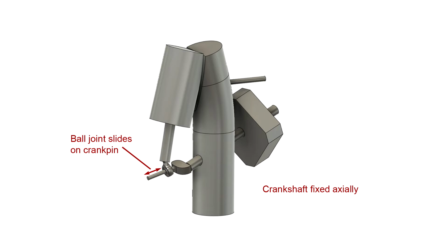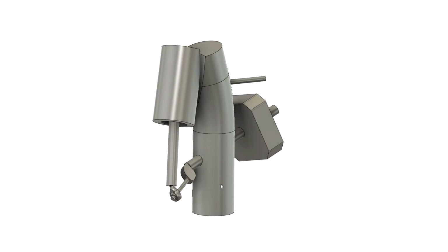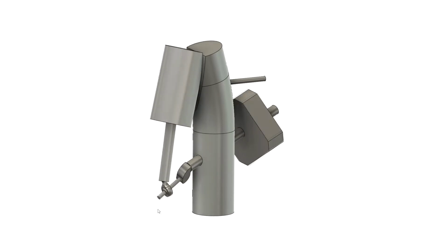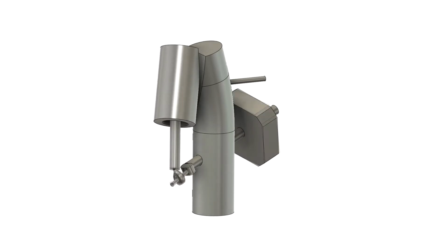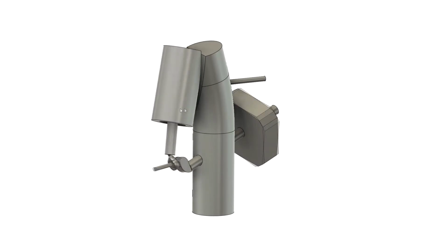Okay, let's try the obvious and let the ball joint slide on the crank pin. It works, and this seems the preferable degree of freedom to relax to minimize friction losses. We need a fairly long crank pin, but that seems okay if it's strong enough to tolerate the bending moment. The kinematics work, and that at least suggests that an engine with dramatically relaxed geometric constraints might run. But kinematic solutions don't include forces, and particularly friction forces, the bane of engines that don't run well or don't run at all.